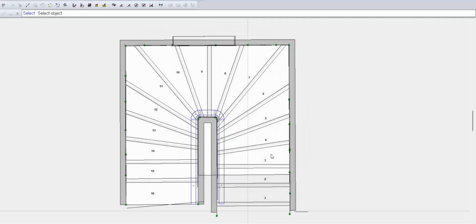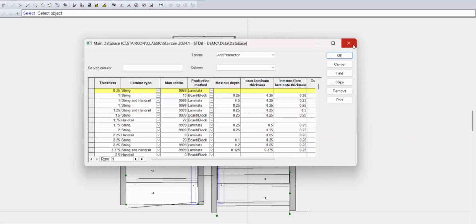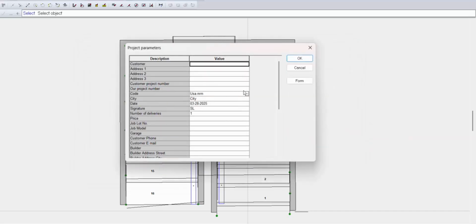We can check, and in these codes we can put in different settings. Even our users can make changes in it. So if you work in different states or provinces, you can just pick the one when you have a new project. You can select which norm to use. Now I had the residential code for US, what we have from the SMA, but it can be any code, and we calculate on the rise run, even if there's a floor opening.